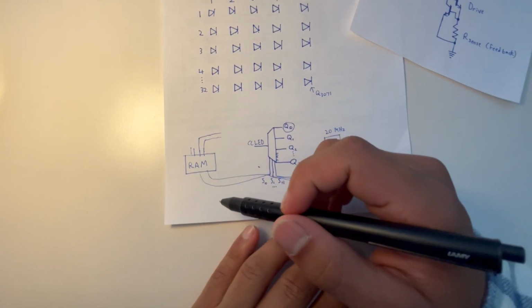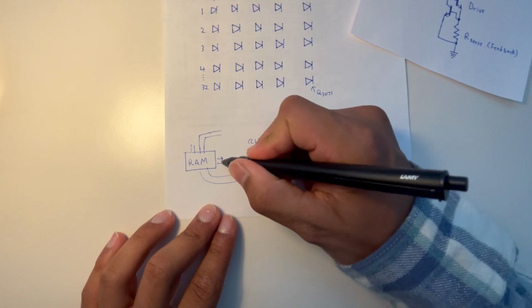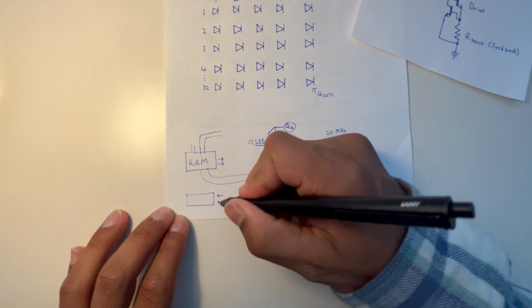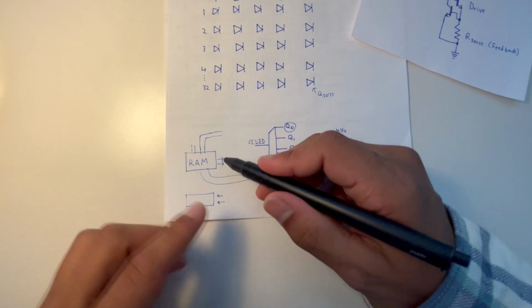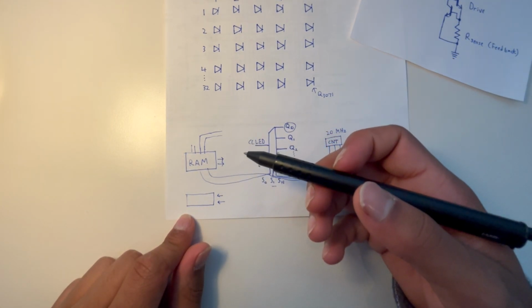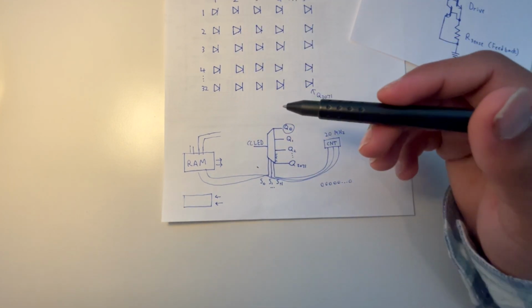Basically, it acts as what's called a double buffer, which means while one RAM chip is being read from, a second RAM chip is being written to. And this changes every time the frame changes, and then they swap using multiplexers. So the result is that the live feed from the camera is put directly onto the matrix.